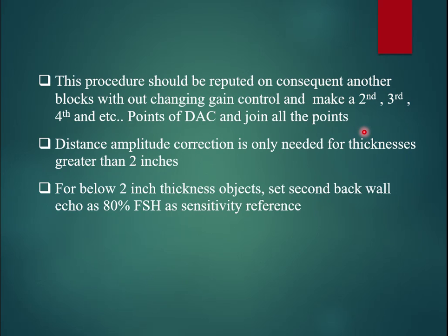While you are catching the second, third and fourth points, you should not use the gain option. You should not touch or change the gain option, meaning you should not raise or decrease the gain, right? So you should remember this point: you should not touch it after catching the first point.